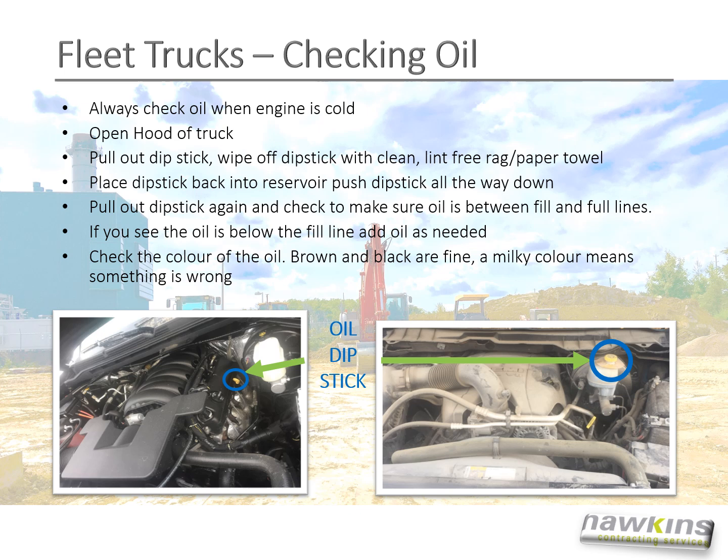If you see the oil is below the fill line, add oil. Check the color of the oil. Brown and black are fine. Milky colors mean something may be wrong.